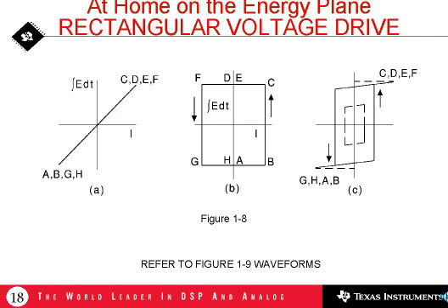What that will mean is when the 10 volts positive is applied, we will move at a constant rate in the vertical direction. How do I know that? Because that's the integral of volt-seconds. If the voltage is constant, then as time goes along, we'll be moving at the same rate in the vertical axis.